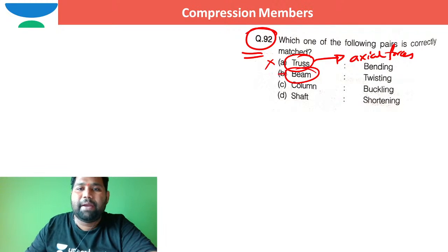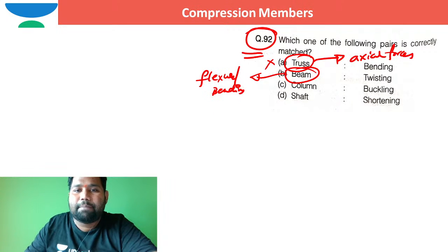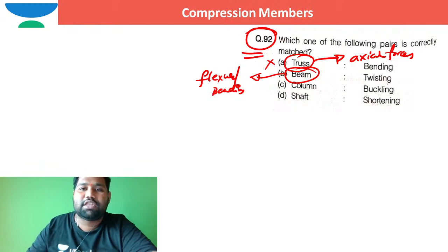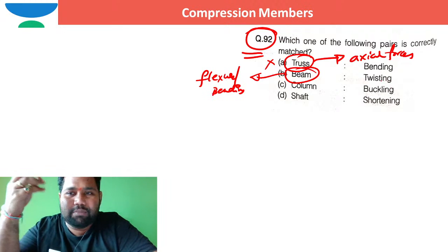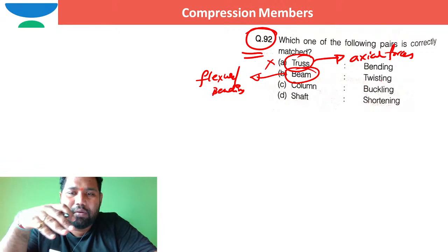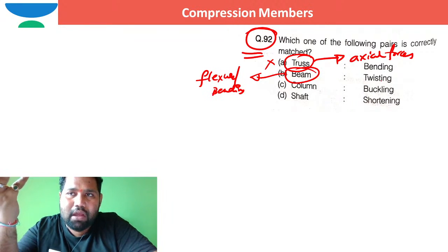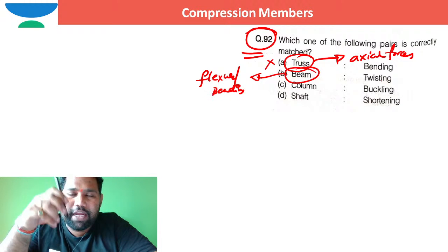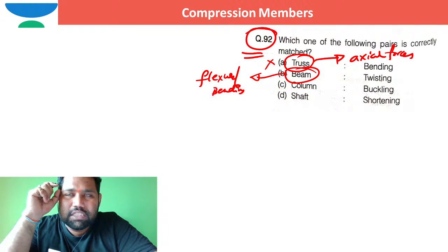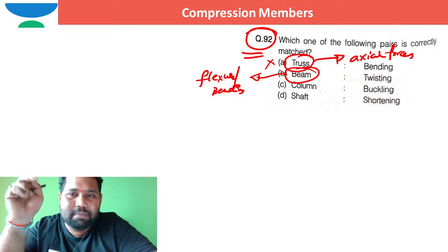In a beam generally bending, flexure, is possible, but here they are saying the primary one is twisting, torsion. In a beam torsion can develop, but the major torsion develops when the CG of the loading does not coincide with the CG of the plane of the beam.